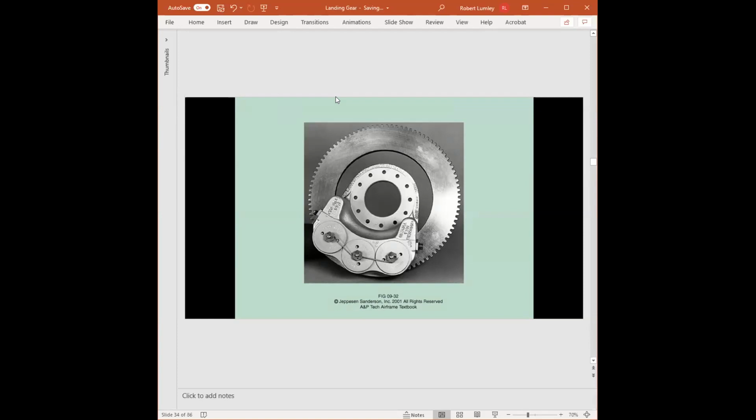I'm just going to make a quick mention that these little centerpieces we'll be talking about are parts of what's known as the automatic adjusters, okay? Besides automatically adjusting the brakes for clearance or adjusting for wear, the little centerpiece we can actually use to measure or to indicate how much brake pad wear there is, so that we can identify when the brake pads are below minimum and need to be replaced.